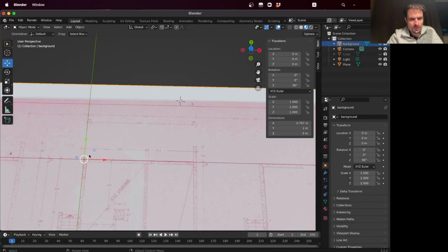So now we need to adjust the dimensions. So we would like to stretch or scale this drawing in such a way that this point here, 3, is at position 3.97 meters from the origin, right? So to that end, the easiest way is to create a reference. So we can, for instance, bring this plane to the origin, this one here.